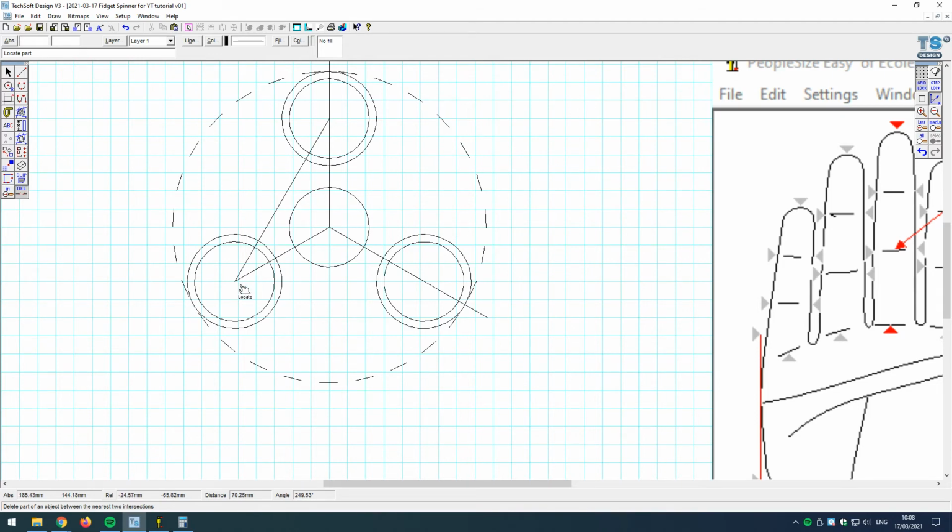to this bearing. In fact, actually thinking about it, I didn't actually have to do that. I got carried away there. The fact that I'm working with this radial lock here means I can just snap that across to there, and then what I need to do, that's why I had to do it, because I wanted to run a line across here. Now, actually, I could just run a line across like this, but to be absolutely precise, let's just trim that line back there as well.